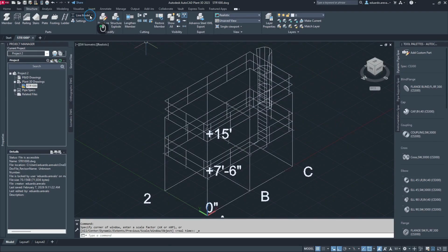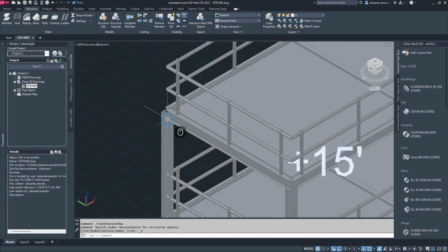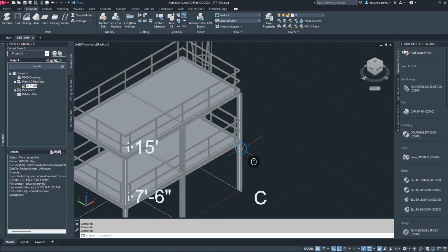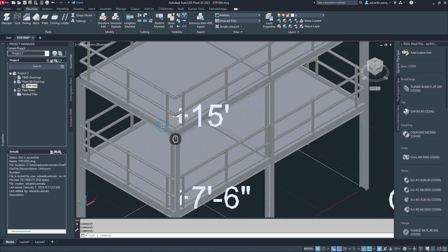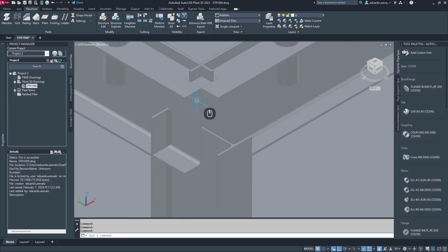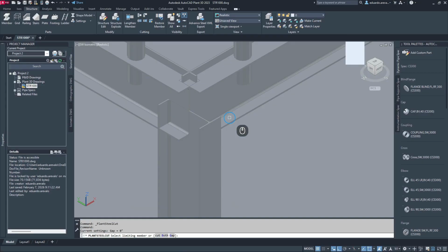After, we're going to go back to the shape model, and as you can see, some end terminations for the joints, for the steel joints, they don't have a lot of detail. They're very raw. They cross each other, they overlap. So there is a way to refine this detail, and for that I'm going to use the cutting panel here. So I want you to come here to the cut back member, and what this is going to do is cut a member with another member.